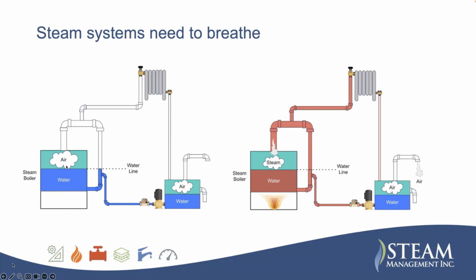So as we start to heat this up and it turns to steam, two gases can't occupy the same space. So the steam forms, it's a higher pressure than air, so it starts to push it out. And it goes up through the radiator, out the steam trap, and out the valve. So it pushes all the air out of here. So now when this thing is hot, it's all filled with steam. There's no air inside here, hardly any air.